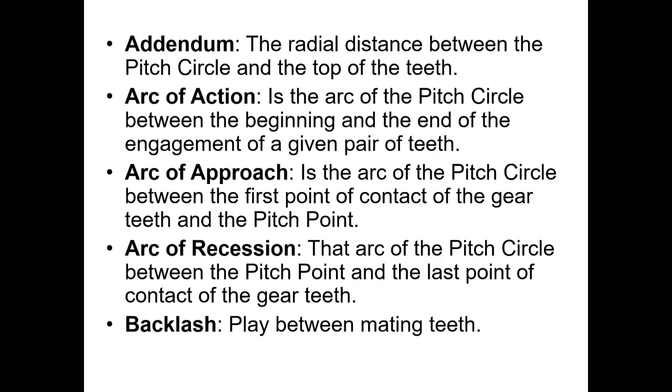Next, arc of approach is the arc of the pitch circle between the first point of contact of the gear teeth and the pitch point. Next, arc of recession is the arc of the pitch circle between the pitch point and the last point of contact of the gear teeth. Next, backlash: play between meeting teeth.